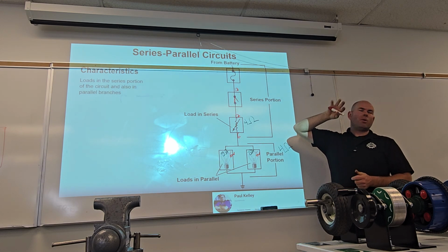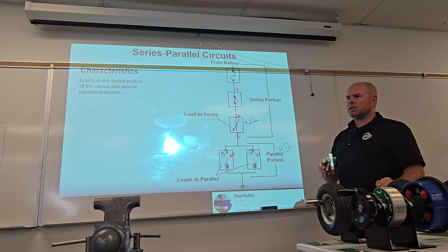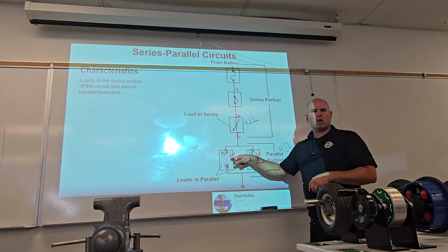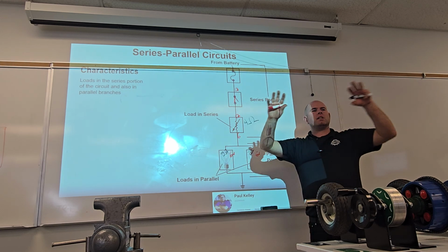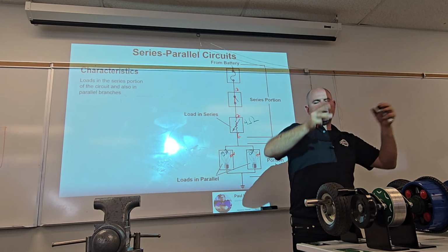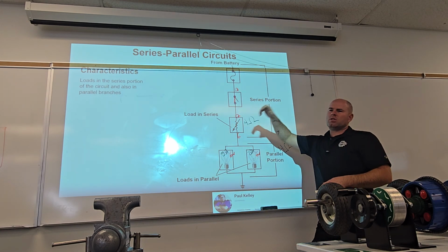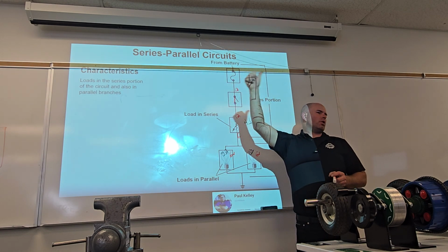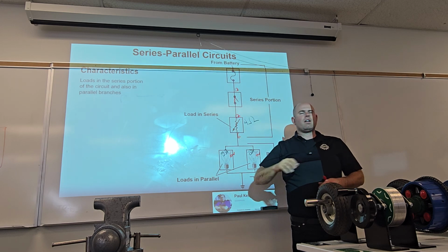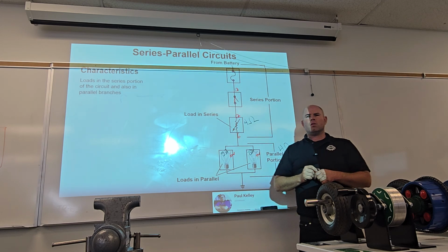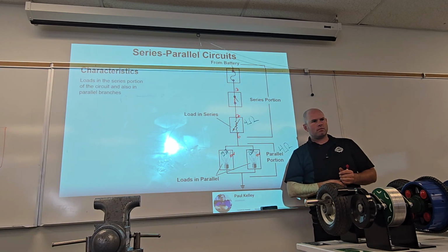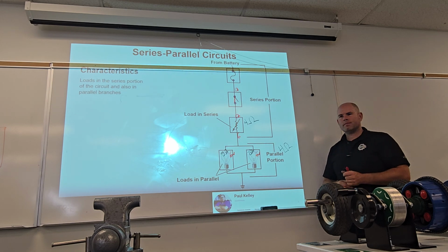Let's say it's a little more practical. A car comes in, it has dim bulbs all the time. All your instrument lights are dim. This instrument panel, your radio, everything is dim. And you go to the dimmer and you turn the dimmer all the way up and all the way down, and all the way up and all the way down, and they're still too dim. What are your thoughts?